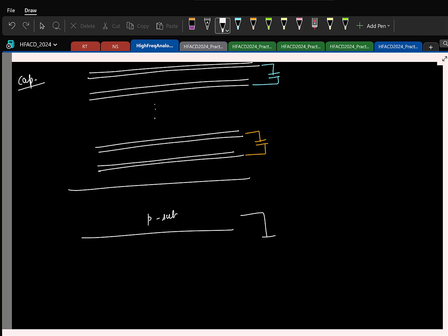So anytime you form a capacitor, you not only have this capacitance formed between the two metal lines, you will also have an extra parasitic capacitor, let us say, from each of the metal lines to the substrate, right? And of course the bottom plate will have the largest parasitic capacitor because it is closest to the P substrate. So if this is the case, which of these two do you think is better?